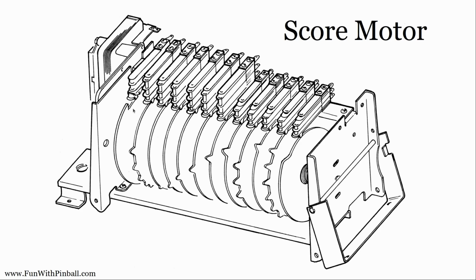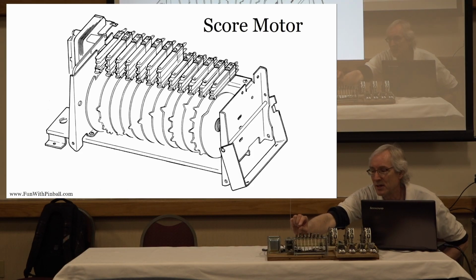Well, this first cam is used, among other things, to keep the motor running to the next gap in that cam. So once I start this motor, I can actually even just push this coil forward. Usually it's a circuit that electrically gets the motor to start. But I can walk this forward enough to activate this first cam, or this first switch here.